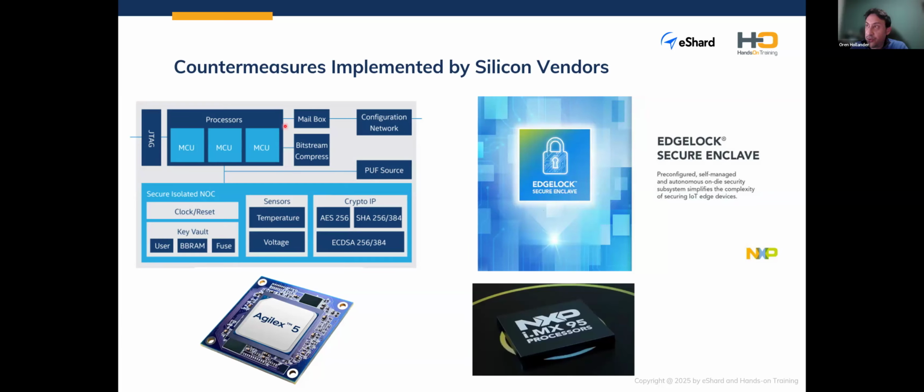This has, as you can see here, triple modular redundancy, 3 CPUs. And that means the SDM logic is duplicated 3 times. If a fault injection, for example, flips a bit in one core, the other 2 cores outvote it, and a security fault is raised.